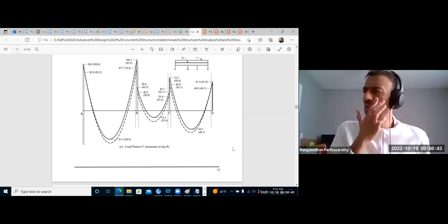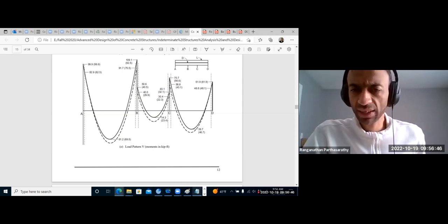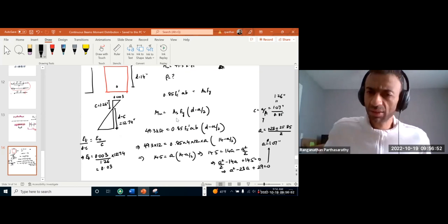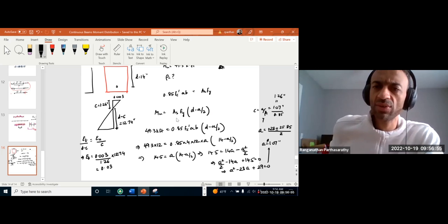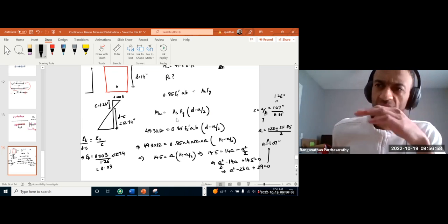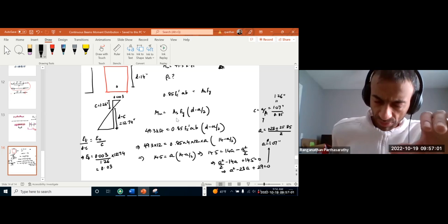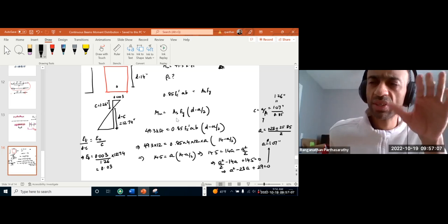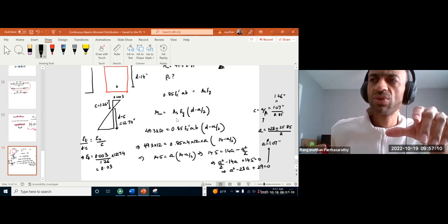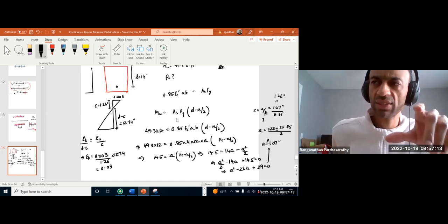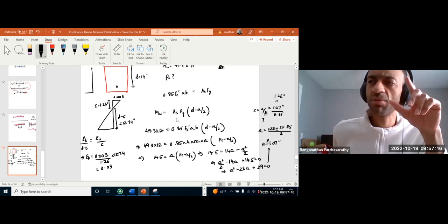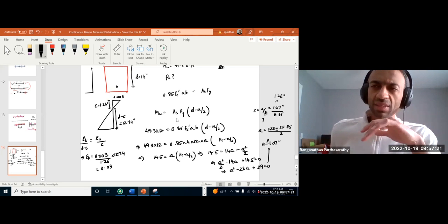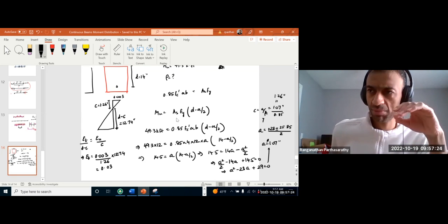Yes. Here what we calculated is just the nominal or design moment capacity. We are just doing it according to the equivalent compression block that we use as usual. Over here, we are not worrying about the curvatures. So you're right. We should actually calculate, if the plastic hinge forms, that the maximum deflections are going to increase. Whether that is still in the permissible limit or not, we must calculate.